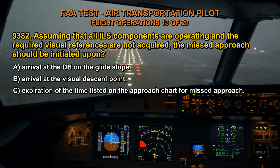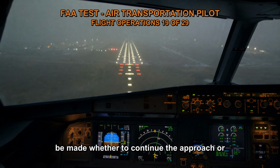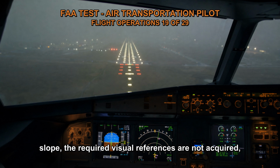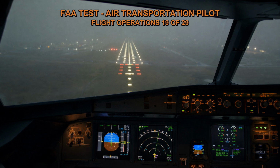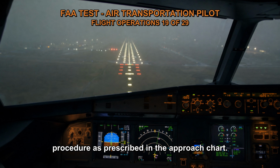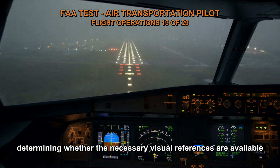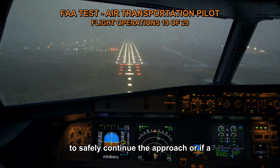The correct answer is A. When flying an ILS approach, the DH is the specified altitude at which a decision must be made whether to continue the approach or initiate a missed approach. If, upon reaching the DH on the glide slope, the required visual references are not acquired, the pilot should promptly initiate the missed approach procedure as prescribed in the approach chart. The DH serves as a critical point in determining whether the necessary visual references are available to safely continue the approach or if a missed approach is required.